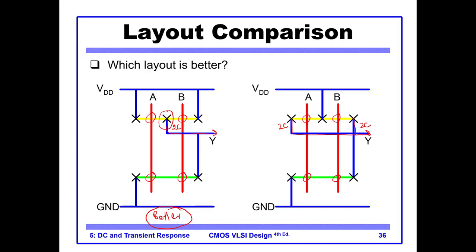Okay, so this brings me to the conclusion of this lecture. This lecture is very important in terms of how we can plug in the RC model, and before plugging in the RC model we need to size the transistors. So we need to determine the parameter K, which is the width, and then we need to plug in the RC model, and then we need to calculate the equivalent circuits for best case and worst case.